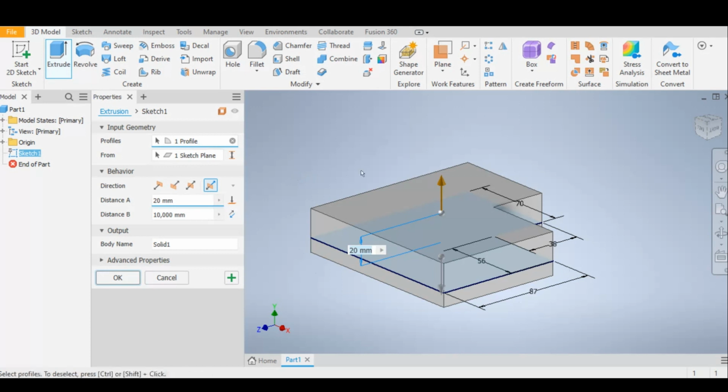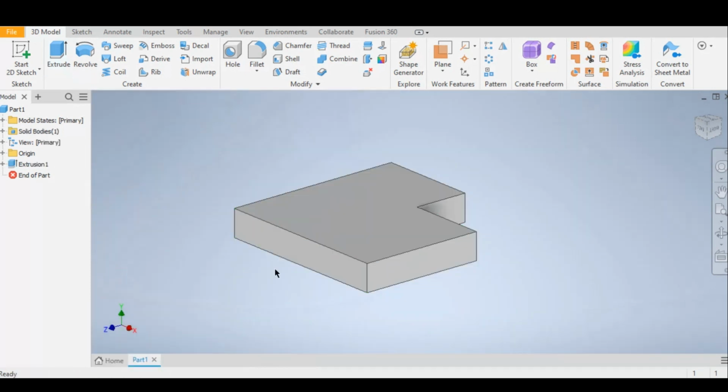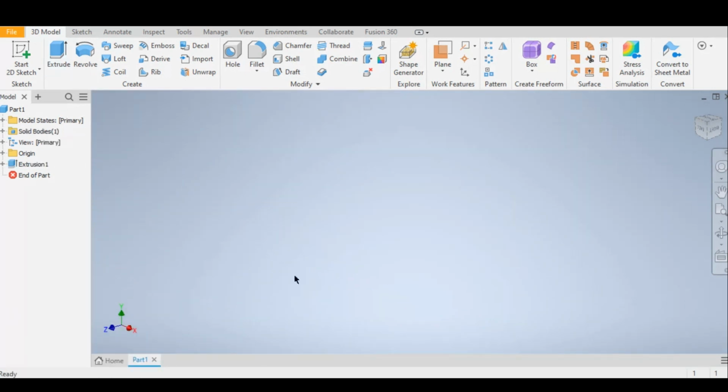So this extrusion will work when you're doing that, but for the sake of this tutorial, we'll just be using our default extrusion, and we will only be extruding in one direction. So as you can see here, once you're happy with our extrude functions here, once you've populated all our properties here, we can simply select OK, and then our first part of this extrusion is complete.